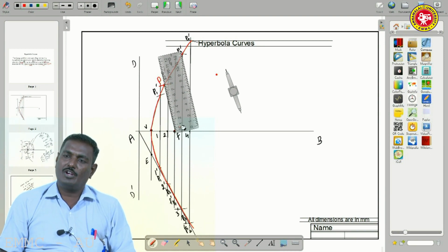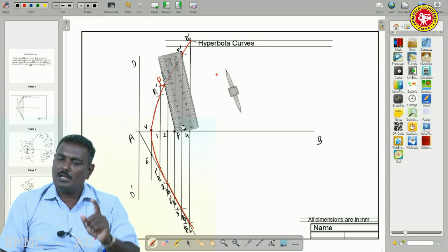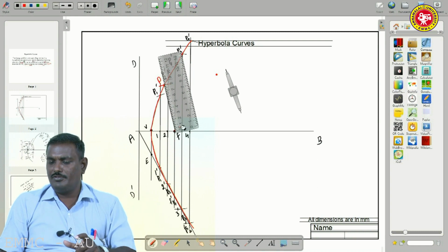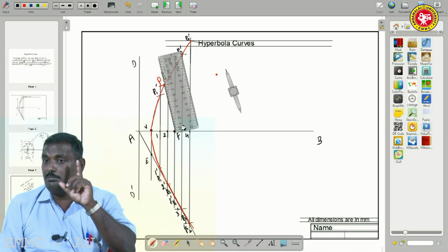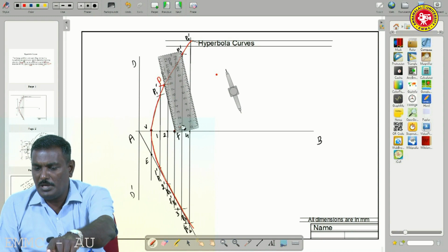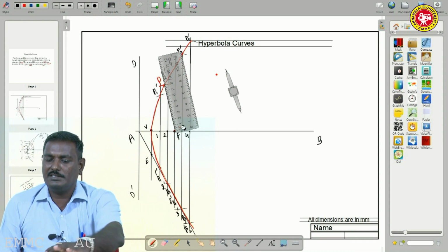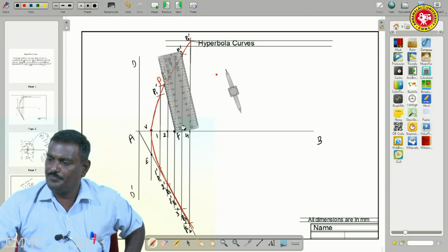So for that we have to draw a perpendicular line from point F to the new locus point capital P and F. For that we draw by using the mini drafter scale. If you place the mini drafter scale in this position, the other scale is perpendicular.